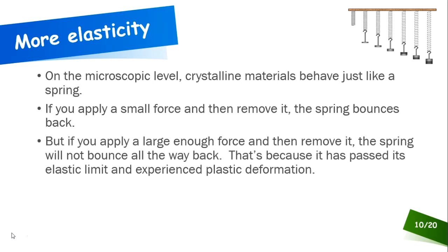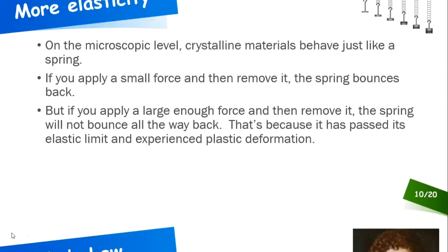But if the force is large enough so that you exceed the elastic limit, then the spring doesn't bounce back all the way. That's because it's past its elastic limit. And now you have what's called plastic deformation. So there's elastic deformation, which disappears once you release the force off your material. And then there's plastic deformation, which is deformation that remains in the material after you release the force. And plastic deformation means that you've exceeded your elastic limit, because that's the only way you can get plastic deformation.